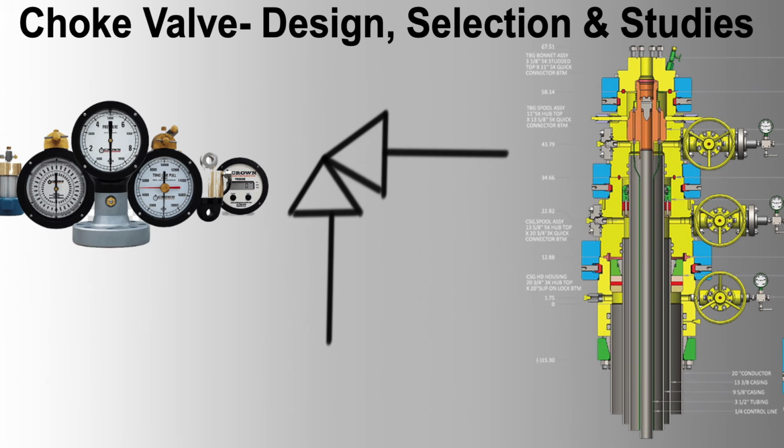4. Stable flow applications. Type fixed choke valves. Scenario: applications with stable flow rates, such as long-term production wells. Advantage: high reliability and low maintenance due to the simplicity of the design. Disadvantage: lack of flexibility in adjusting flow rates limits operational adaptability.